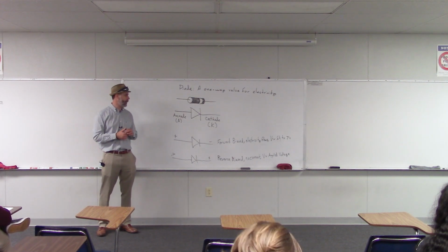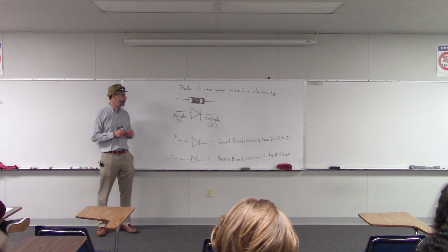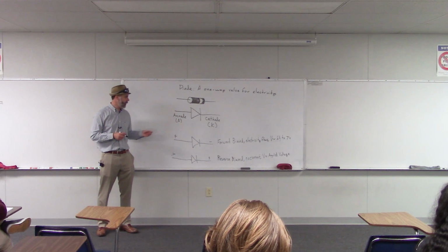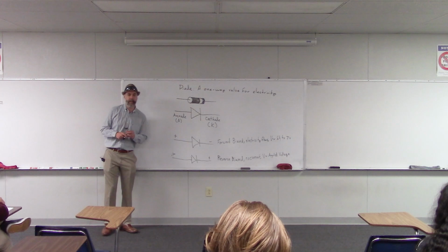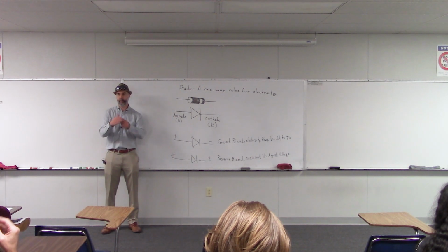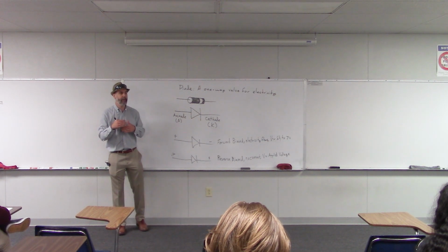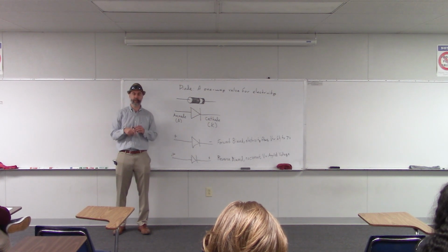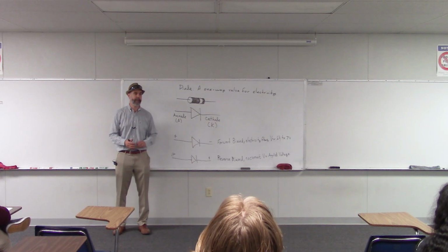Another example of how diodes can be useful is that they can be used in a protection circuit. So, for instance, if you have a little chip that's very sensitive and it can withstand voltage that's applied in the correct direction, but maybe that chip would blow up or get damaged if the voltage was plugged in backwards by accident, you can use a diode to protect that chip.